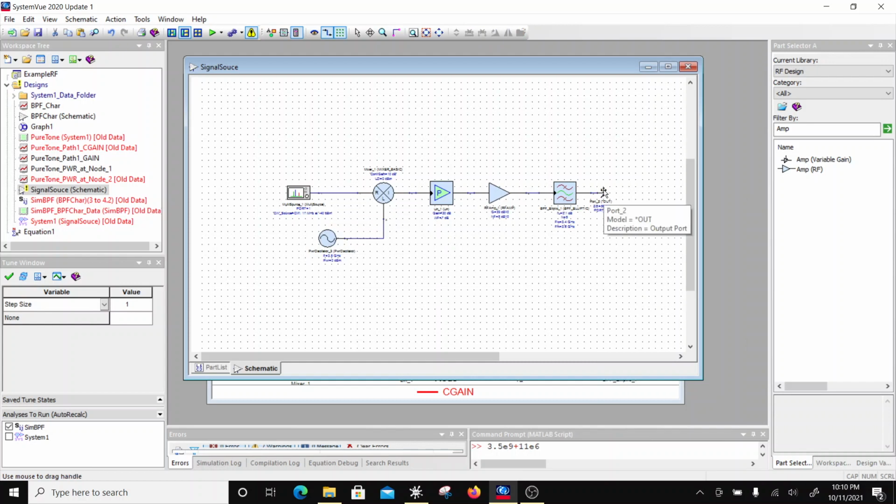So the budgeting on a transmitter is more of a gain budgeting, power budgeting, or a linearity budgeting, while on a receiver it's more of a gain budgeting and the cascaded noise figure budgeting, because here you are more concerned on a receiver for signal to noise ratio and the sensitivity and the TOI, right?